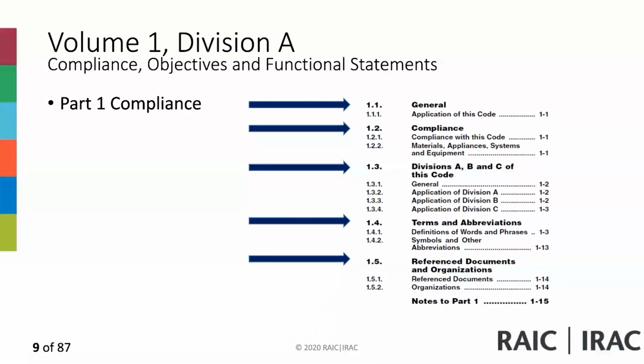Parts 3, 4, 5, and 6 apply to all buildings, including buildings classified as post-disaster, all Group A assembly buildings, all Group B care, treatment, and detention occupancies, so basically long-term care and hospitals, Group F Division 1 high hazard occupancies, any building that exceeds 600 square meters in building area, or exceeds 3 stories in building height and is used for major occupancies Group C, D, E, and F Divisions 2 and 3, which are medium hazard and low hazard.